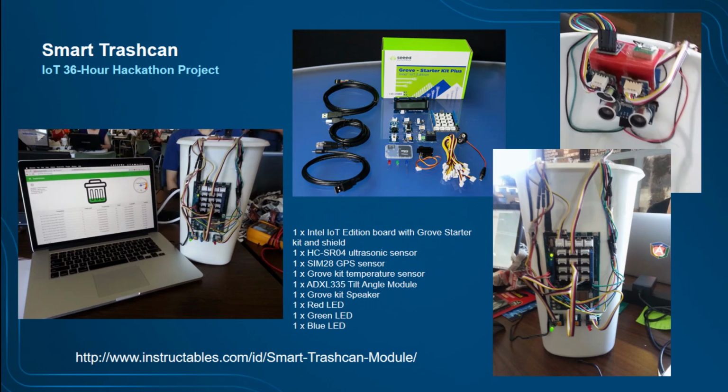We used an Intel Edison, brought a plastic trash can, and connected a few sensors that you see on the list. We have an LED and temperature sensors. We have GPS to tell the position or location of the trash can. We have an ultrasonic sensor that can detect whether the trash can is getting full or not.